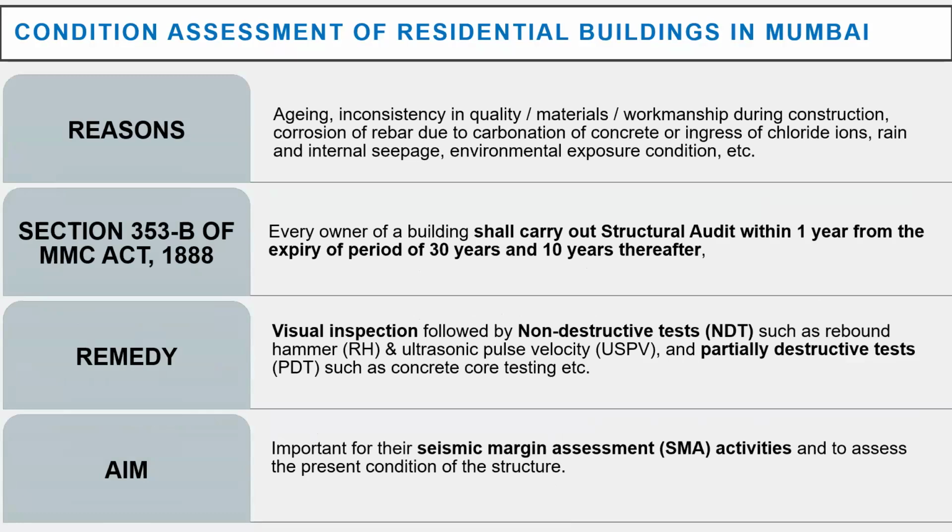Here, one thing I would like to mention is Section 353B of the Mumbai Municipal Corporation Act 1888. This act says that every owner of a building shall carry out a structural audit within 1 year from the expiry of a period of 30 years, and every 10 years thereafter. In the previous slide, I showed the frequency of carrying out NDTs and PDTs on the existing structure based on the BARC safety manual. So both align well.